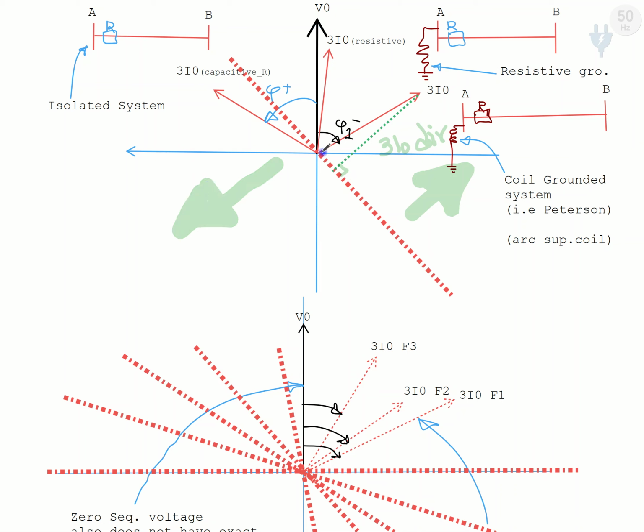But the question is that we have some amount of zero sequence current, for example, this amount of zero sequence current during the operation. Even then we have some zero sequence current. So if we select it as a zero, and if any value of zero sequence current increases by 2 amperes or 3 amperes, then our system will operate even though there is no fault. During the operation it will operate and it will trip, maybe it will pick up. So let's